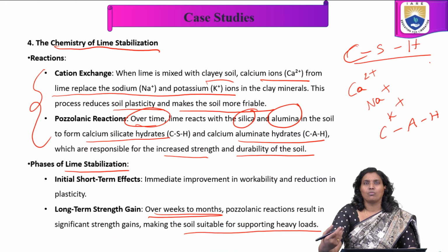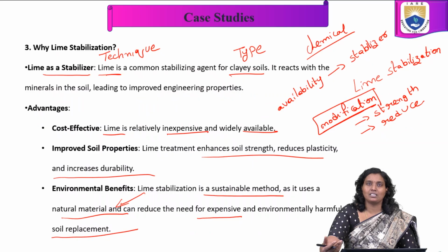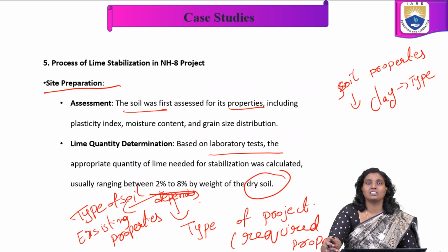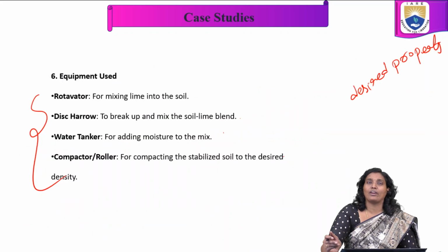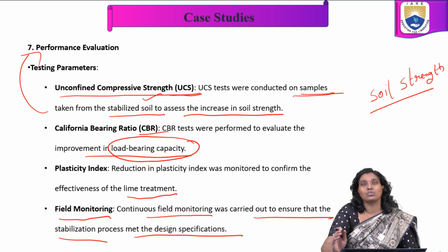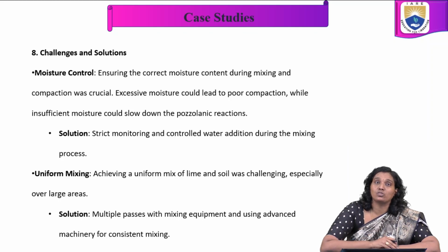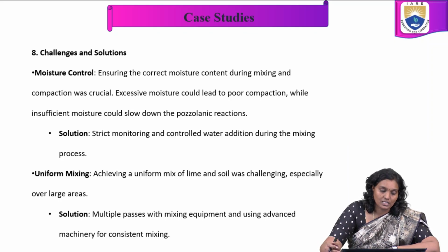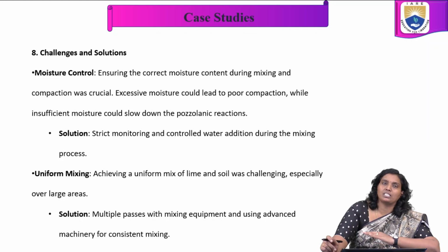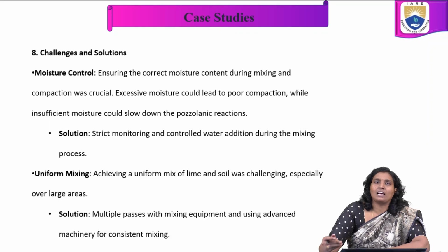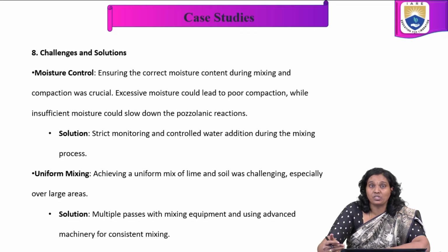So now, why lime stabilization? And what are the reactions that are involved? What are the phases? What is the process we will follow, and which kind of equipment we are using? How the performance analysis using their test parameters. And in this, what are the various challenges and their solutions in this lime stabilization process? Moisture control is one of the challenges, and also uniform mixing. These are the major challenges which we observe in this.